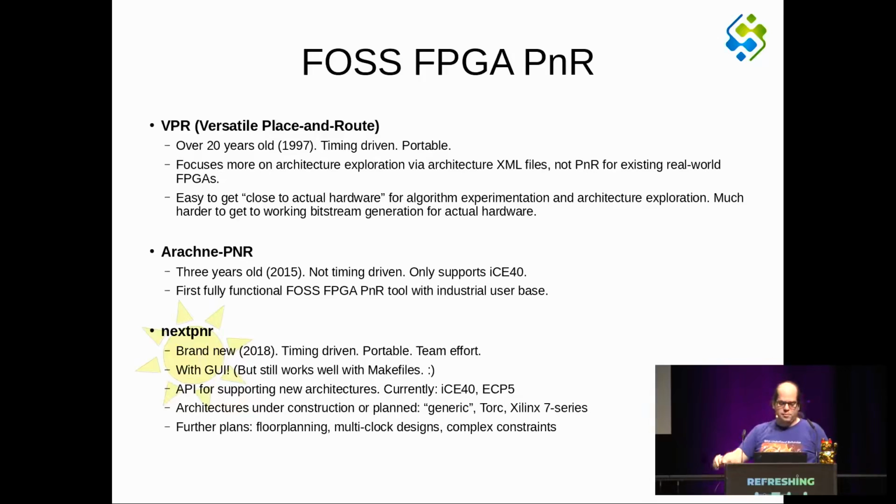So there is VPR, which is about 20 years old. It has timing-driven algorithms. It's fairly portable in terms of porting it from one FPGA architecture to another. But the focus of VPR is more on architecture exploration, so it allows you to easily try out different variations of your interconnect architecture, things like that.